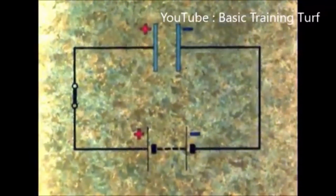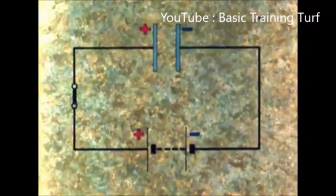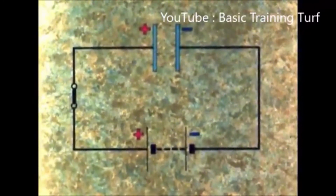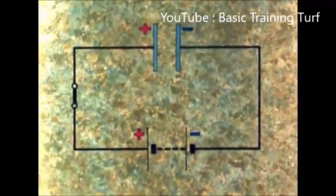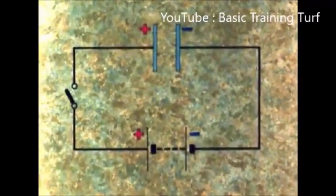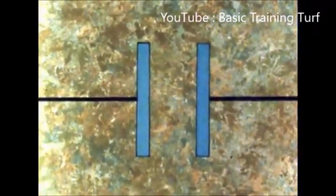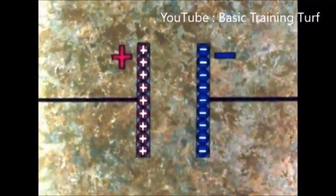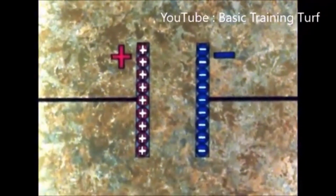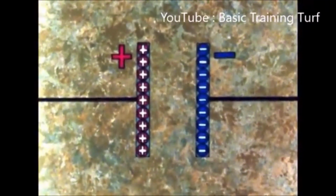Eventually, the flows will stop when the potential difference between the plates is the same as the voltage applied by the battery. The capacitor is now said to be charged. If the switch is now broken, the charge remains on the plates and the capacitor is storing an electric charge. When charged like this, the capacitor is rather like an electric cell with a positive and negative terminal, and in fact it will behave like one for a short time.